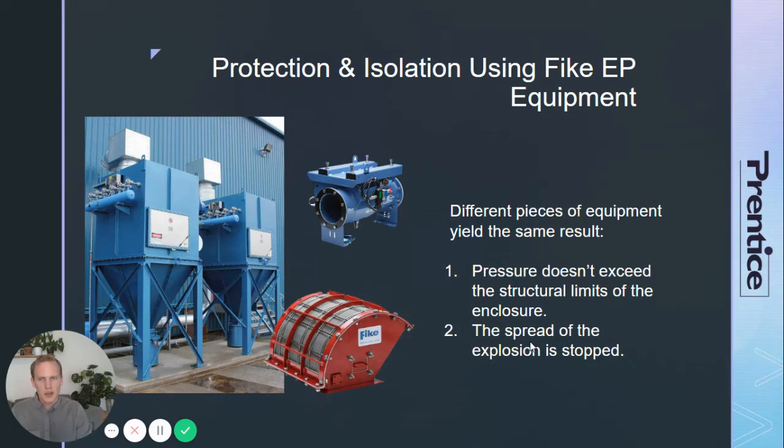You can see those stainless steel rectangles on these blue dust collectors. Those are explosion vents. When there's a deflagration in those enclosures, all those are going to do is open at a predetermined pressure and allow excess pressure to be relieved, instead of having the enclosure itself yield because of the pressure. So what you get is a big fireball shooting out instead of the metal completely being destroyed and shooting shrapnel and potentially injuring and killing someone.